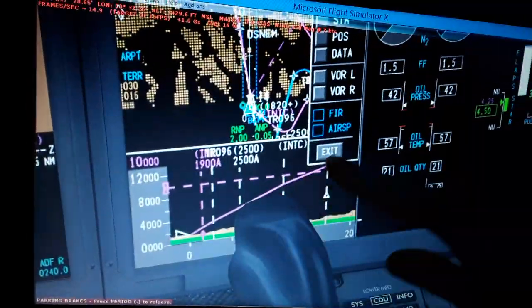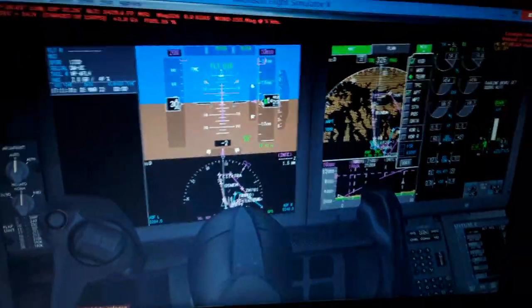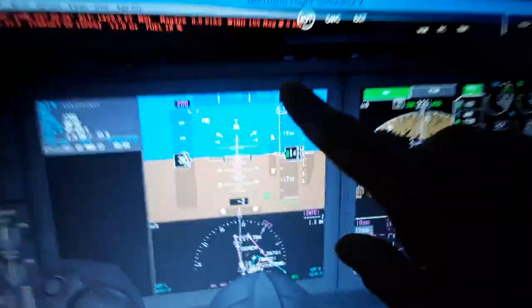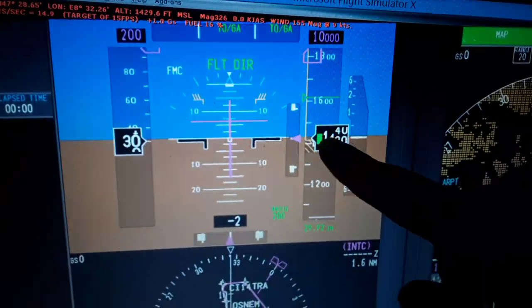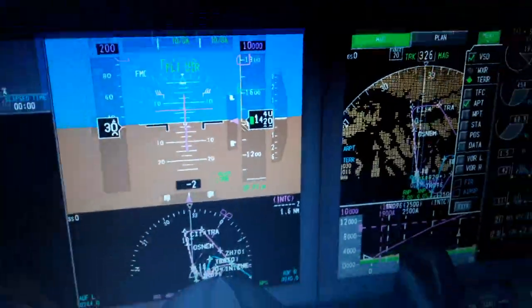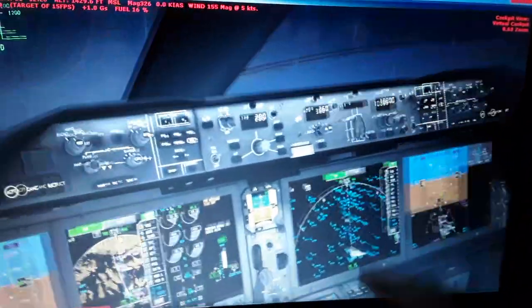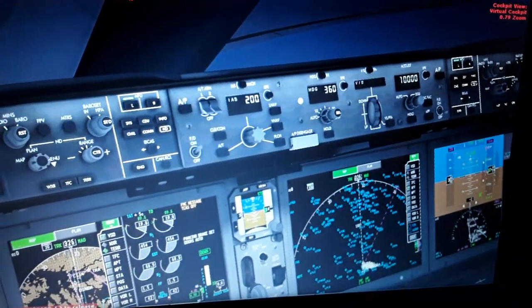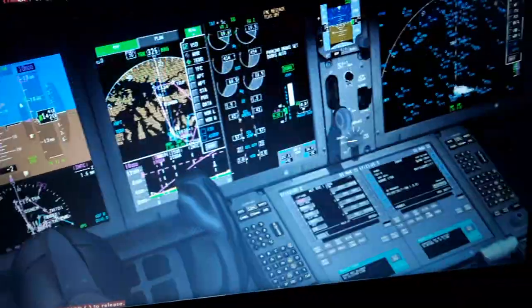The climb over here, the rate of climb, and the slope we can see, the airspeed selected, and the altitude selected from the autopilot flight director system panel, the airspeed indicated and the altitude, barometric altitude. Also we have the flight plan here in the HSI, the decluttered display, first intercept after takeoff. So we have the same airspeed and altitude and heading over here, like on vertical rate of climb, descent, auto throttle left and right, autopilot engage, disengage. So you're gonna see all the functions of the autopilot, also the thrust levers.